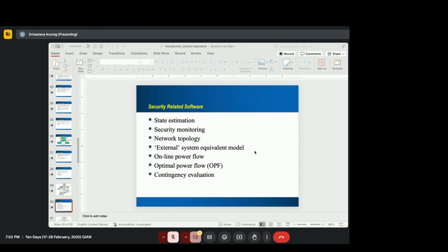1 microsecond accuracy, and even higher, we are able to observe how the signal is rotating on the phasor plane. And if we can observe it, we can measure the angle, which is basically the rate of change. And once we have the measured angle, we can put together an estimate for the phasor with the phasor measurement unit, which is not possible with SCADA.